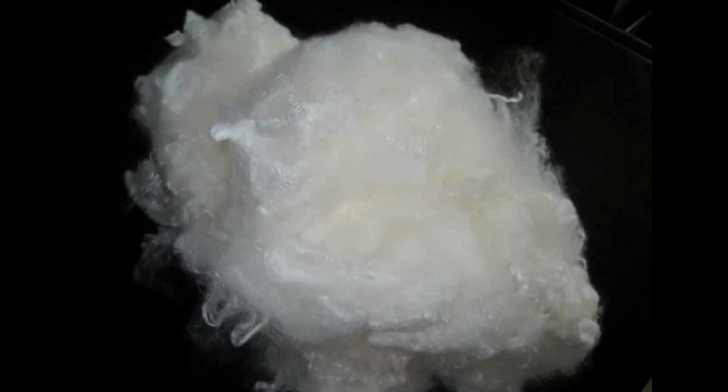When you take the delustering agents, the filament can reflect the light back totally, and thus it becomes shiny, because these come out of the spinneret holes, and this will be very smooth, unlike all the natural fibers.